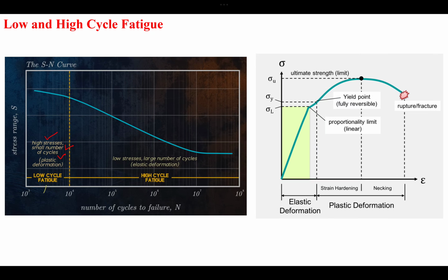So if you look at this stress strain curve on the right, you would see if you are applying something like, for example, this much stress, your body is going to fail here, and this is actually in our plastic deformation region. Okay, this is in the plastic deformation region, which is between this and this curve.